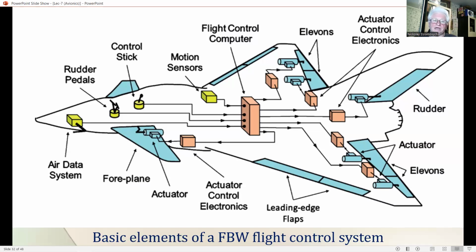For example, in fly-by-wire aircraft, the rate gyros and accelerometers provide the aircraft motion feedback, which enables a maneuver command control to be achieved and an aerodynamically unstable aircraft to be stabilized by the flight control system.